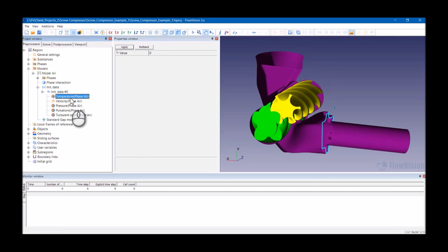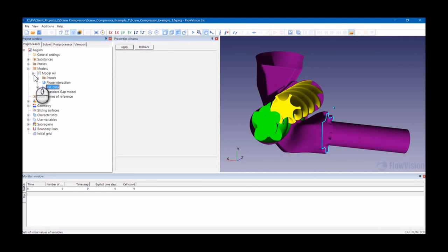So here the temperature is 100 degrees centigrade. Velocity, we don't touch the velocity. Pressure should be 200,000 pascals. And these should be left as 0. So now we have defined the initial data, we need to import the object that we're going to use to initialize this data.